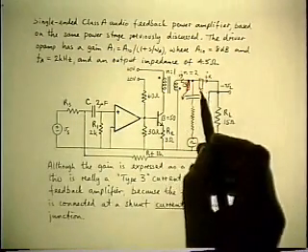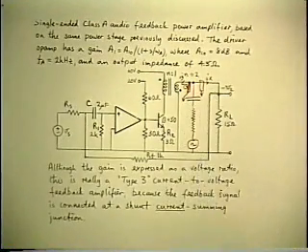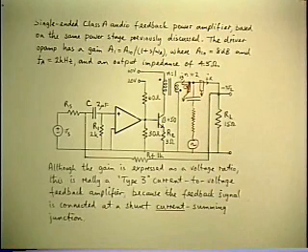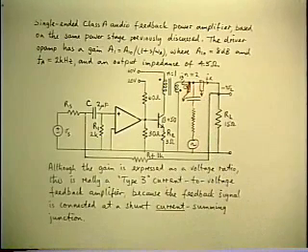And you use them in the normal manner as current measuring devices. You put them into the terminations or the amplifiers, and you convert the outputs to voltages, and you measure magnitude and phase using exactly the same instrumentation as before. So it's actually easier to implement current injection than voltage injection. Okay, so that's all I need to say about that.